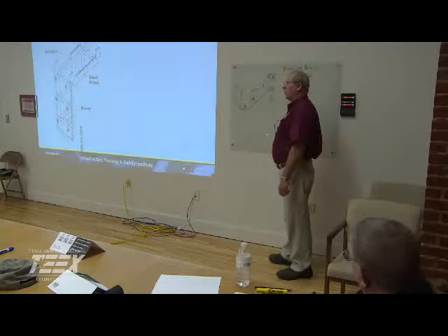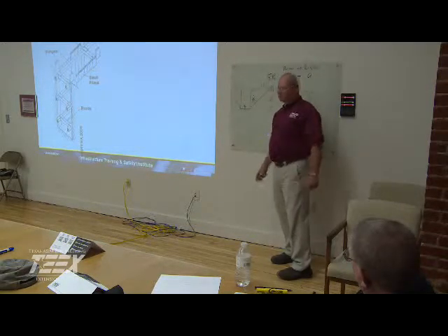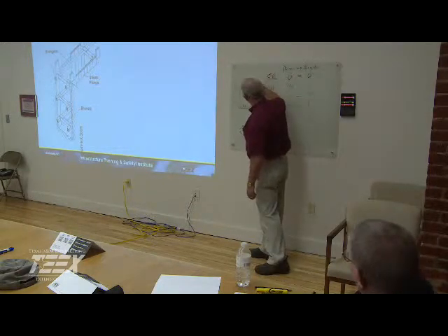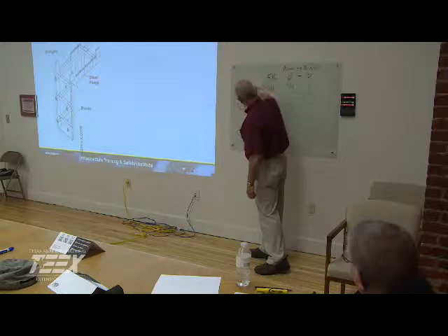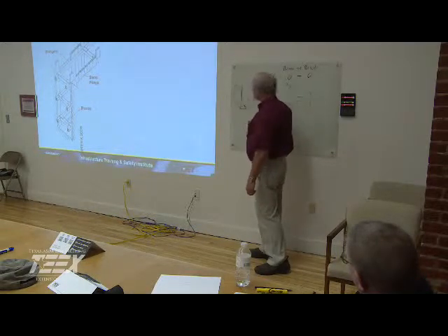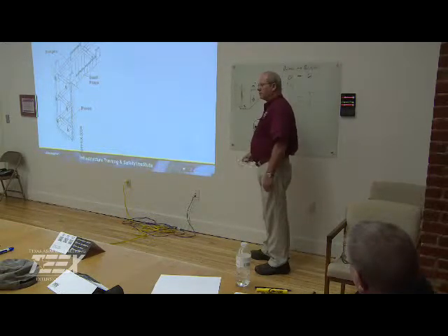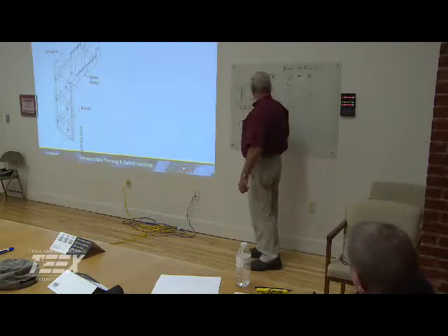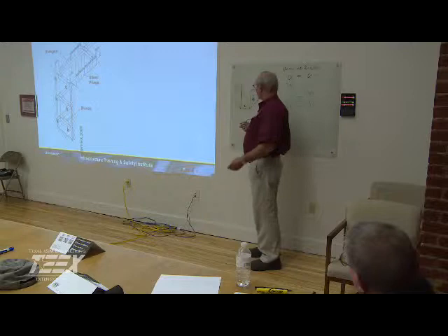We used to call it the angle of repose, yes. But if you come in here and you use a trench box, then the trench box should extend at least 12 inches above the rim of the trench. And also you must have a ladder. Any trench that's 4 feet or deeper, you have to have a ladder.